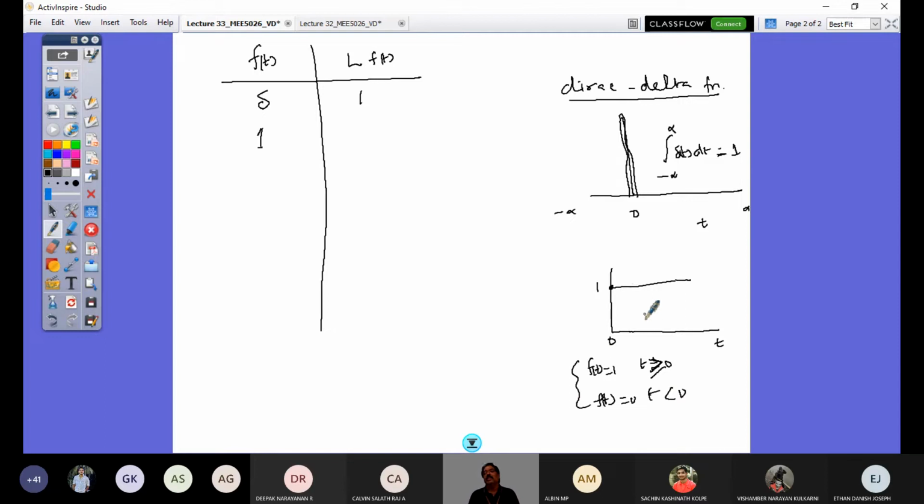So what is the unit step function for your passenger car? When you drive straight on the skid pad, a very large flat surface of a test track, you go with your vehicle straight and then you give a sudden steering input and hold it. That is the step steer input. At t equal to 0, you give the steering input and hold it constant throughout.